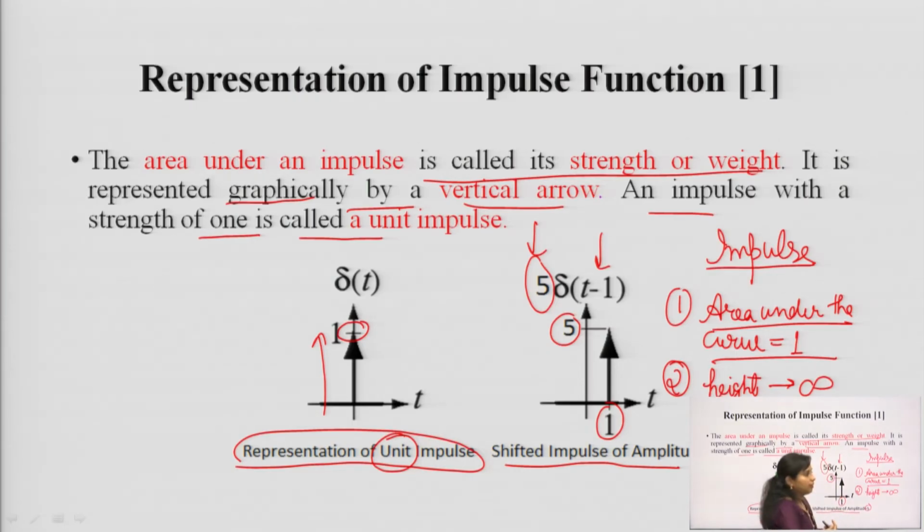Another thing is that whenever we are processing a signal, whenever we are modulating, in case of digital modulation, let us say pulse code modulation or ASK, FSK, PSK, then we have to multiply the input signal with a carrier signal. In that situation, the impulse function comes into the picture, where you have to multiply the input signal with a train of impulses.